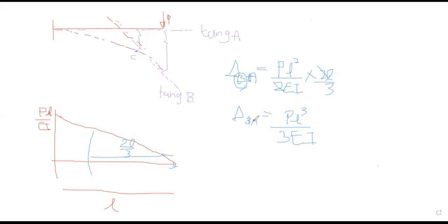Why? The tangent at A is horizontal. So if you want to find deflection, make two points, but make sure one of them is where the tangent is horizontal, actually, right? So if you found two tangents where both tangents are not horizontal, your life would not be very easy, right? So one more thing is we do an example like this. So this is the Mohr's second theorem, right?